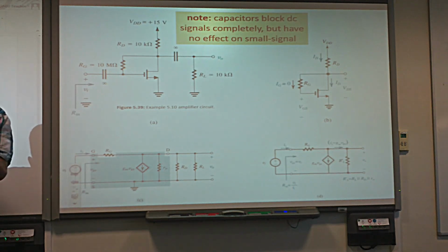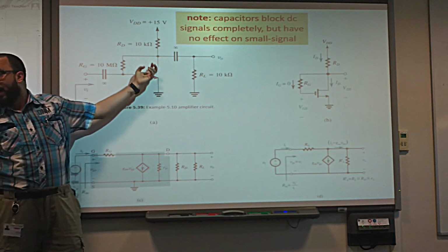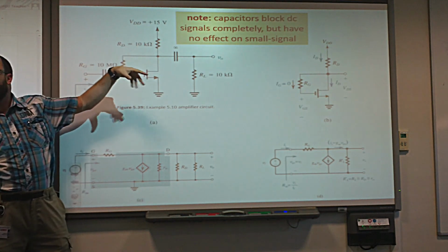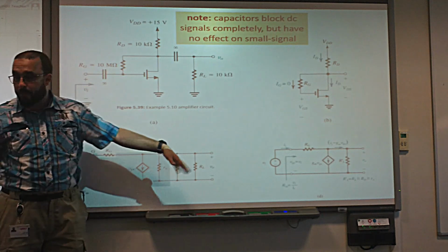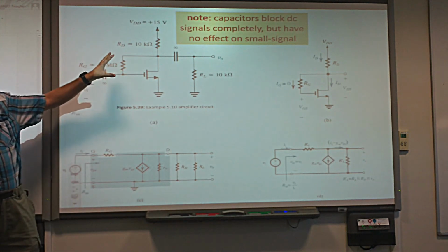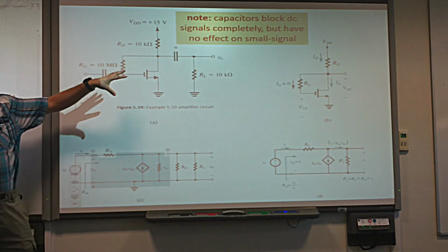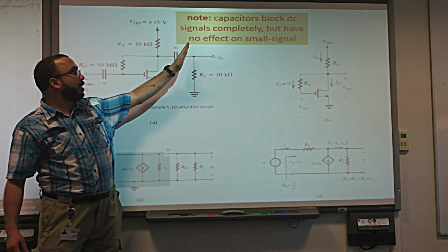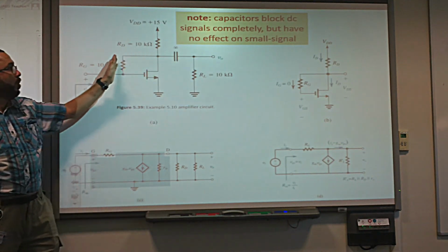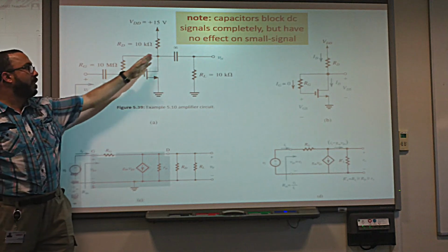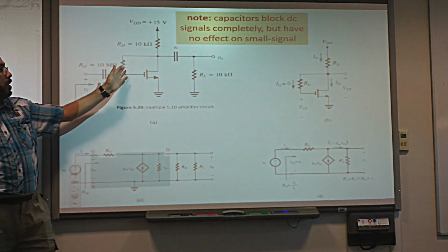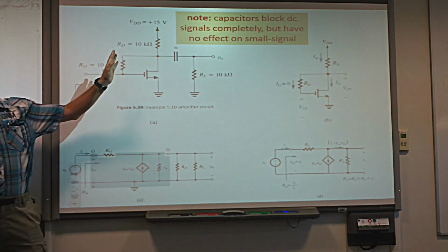So in real life, how do we use a MOSFET amplifier? Basically, we have a MOSFET biased through a voltage supply and some resistors here and there. Don't worry about this circuit. We will come and study it again. Worry only about what I'm telling you here. If you use a MOSFET as an amplifier, you always have to put a large input capacitance and a large output capacitance to not disturb the DC voltage at the input and the output of the MOSFET amplifier. Because if we change the DC, we change the model.